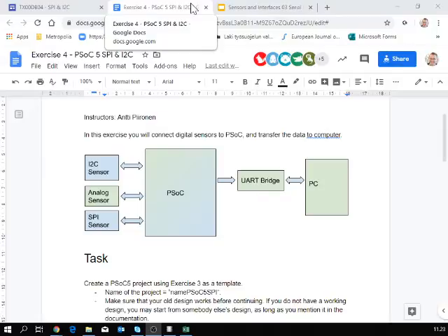In addition to that, you would probably need some capacitors, yes, bypass capacitors. Okay, so that's for the SPI, and of course wires. By the way, with the I2C, you need pull-up resistors. So pull-up resistors for the I2C. Okay, next. So those are the devices.